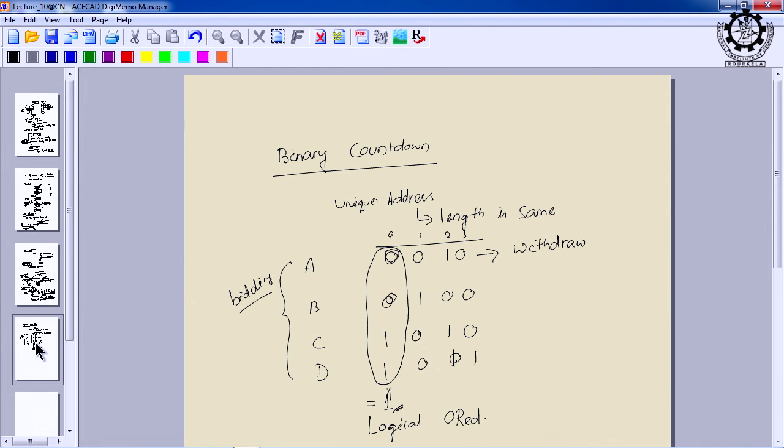So, what happens? Now, this node and this node, both of them withdraw. That means, during the second announcement, they send nothing. So, who else enters into the bidding? Only these two nodes. The second high order bit is 0 and 0. What is the result? 0. So, whatever they have transmitted and the result they match. So, there is absolutely no problem.